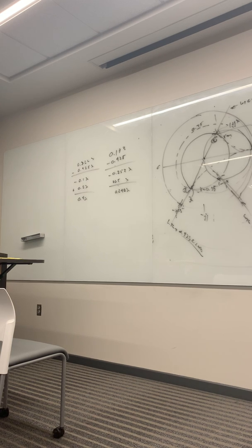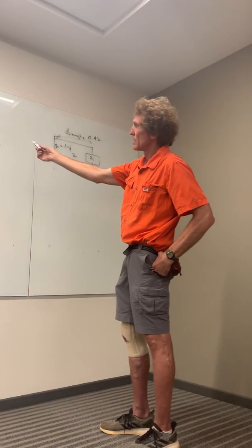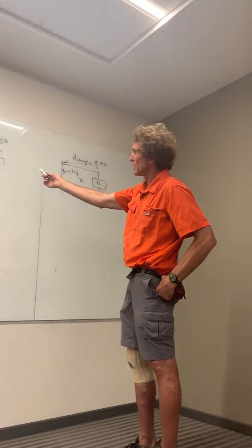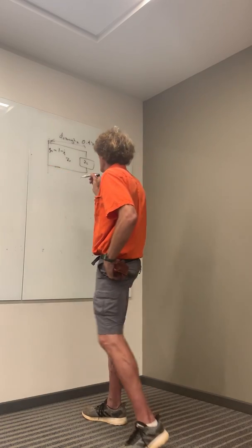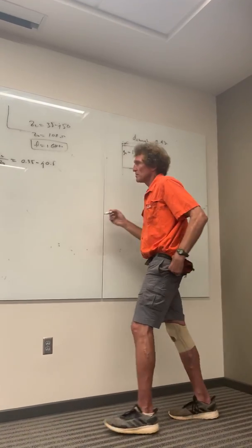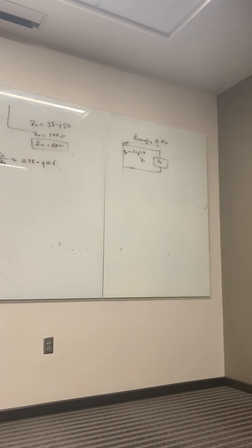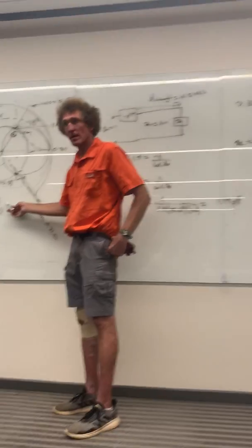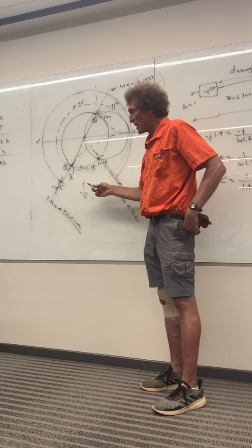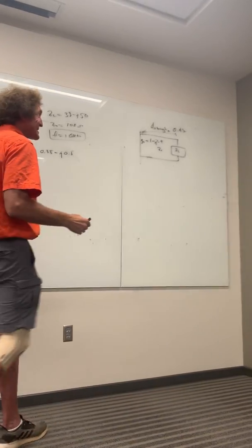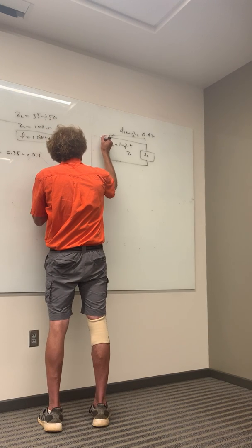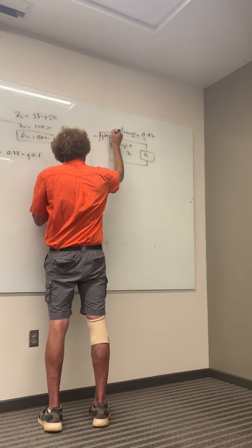And now, at this point, the actual normalized input impedance is going to be 1 minus J 1.4. Isn't the input impedance right here at this point? It's 1 minus J 1.4. Is that right? Yeah. Okay, now what do I need to put in series with this? I have to put in an element that has a plus J 1.4 value.